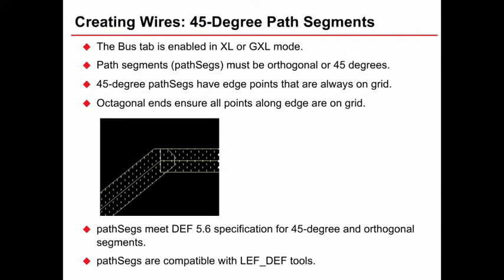So here's a little bit about 45-degree segments. Notice here, as these two center lines connect, that we've made this end fill in that gap. So if they were flush, we'd have a notch there, and so you'd have a design rule violation. So that actually is taken care of by that particular space and that particular rounding or wedging of the tip.